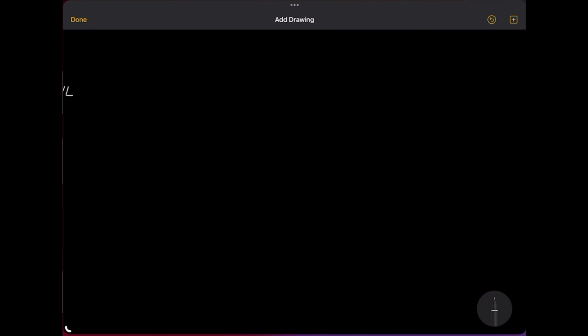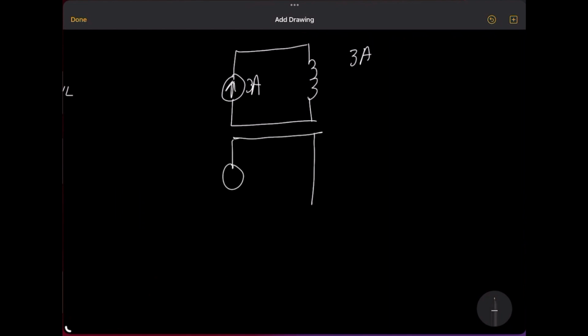A rule is that as an inductor reaches a steady state, a state in which the current is now constant, because as time passes, if this is introduced to a current source, say you just added this current source to this inductor, it's going to resist that change until it's finally going to be at 3 amps fully. And when it finally reaches that point, it's just going to be short-circuited, like so.